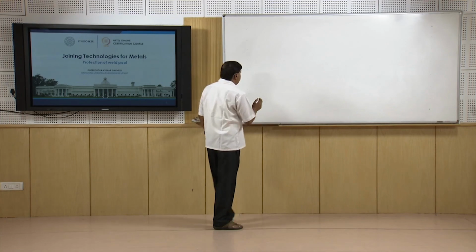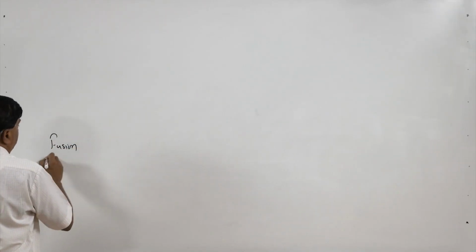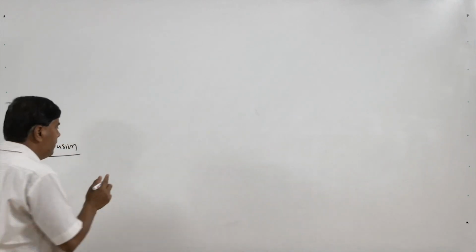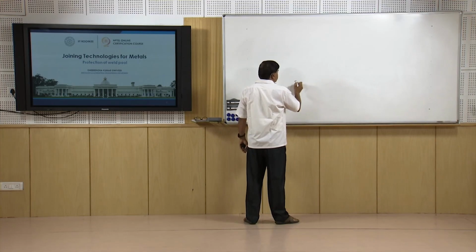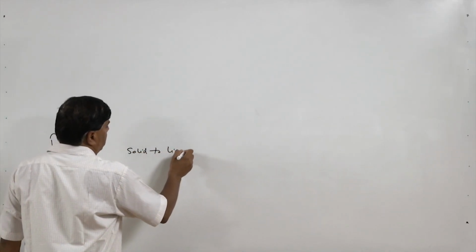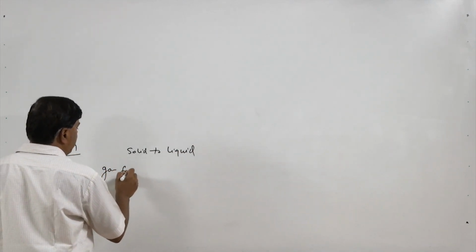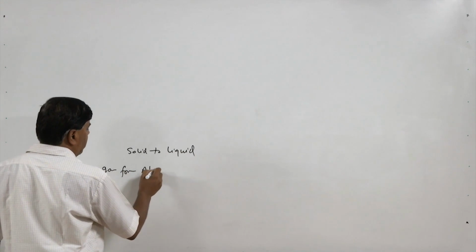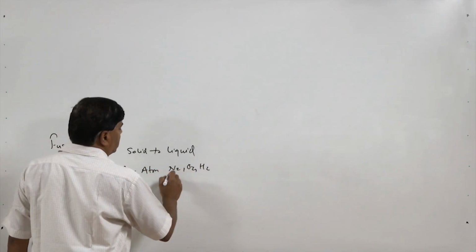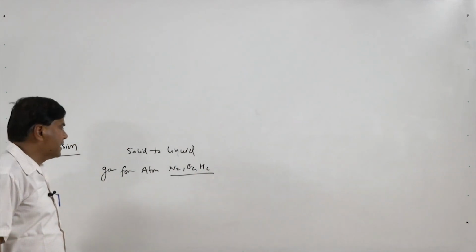So, here when we talk about fusion, because of the change in state from solid to liquid, these gases from the atmosphere like nitrogen, oxygen and hydrogen are the main problematic gases as far as fusion welding is concerned.